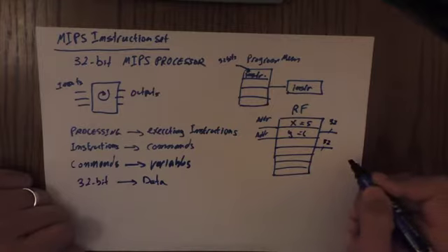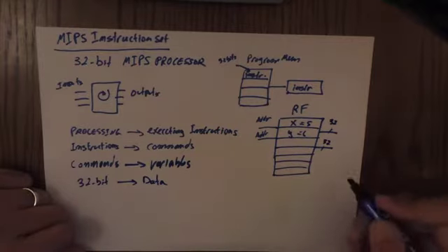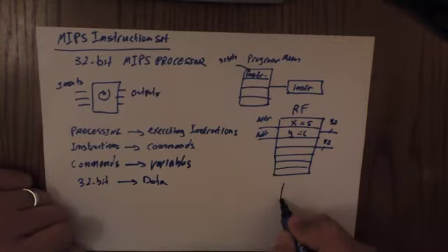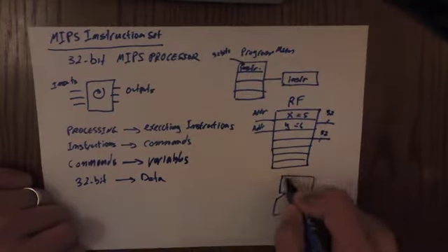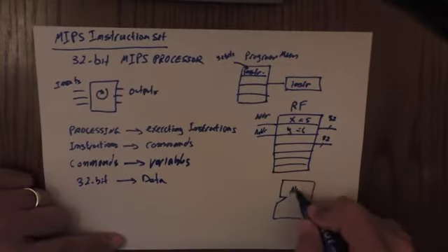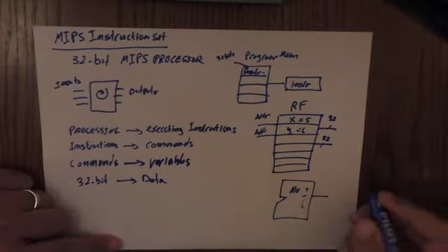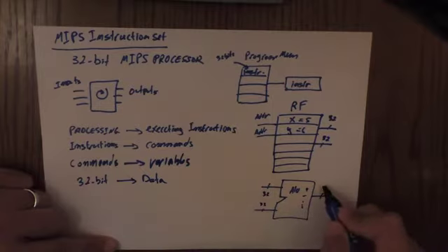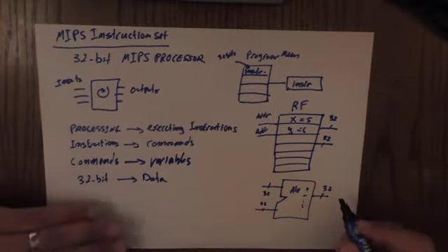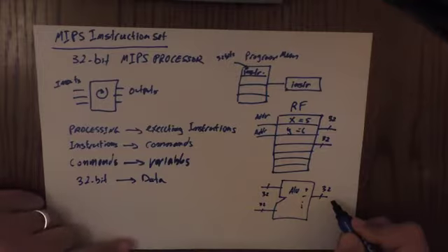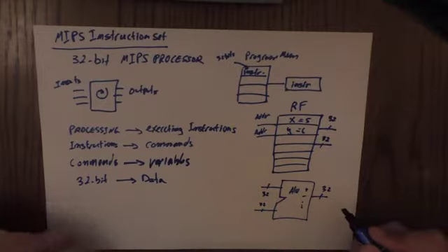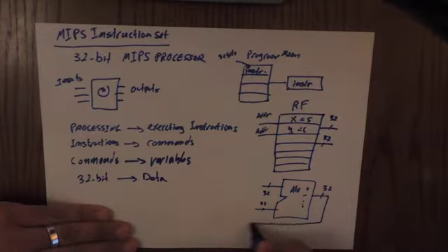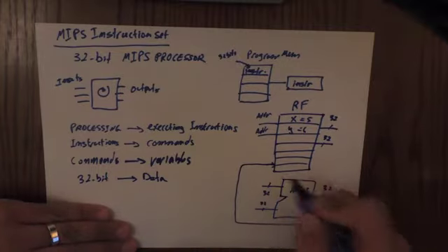Now, of course, we need to add, subtract, and do all these logical operations, so we need an ALU. In this ALU, we can do the addition, subtraction, and all these operations, and then we have the data. Of course, the ALU takes two inputs, each of 32 bits, and generates an output of 32 bits. This value should be saved, and where we save our variables is in the register file. So this line will go like this inside the register file.